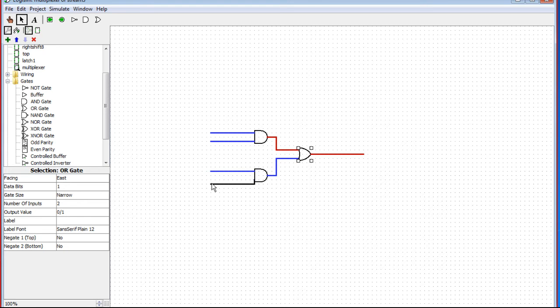Well, that's actually a good question, because I've asked that question myself. I'm like, why would you need a multiplexer when you could just connect a bunch of tri-state buffers to a bus and just select which tri-state buffer you're driving the bus with? And the reason why I'm using a multiplexer is because it's going to make our circuit diagram less messy, and because it'll use fewer components in the simulation, and so it'll allow us to run the simulation faster.